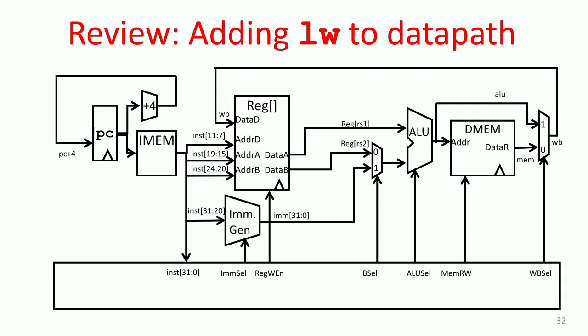The difference is now something's going to come from the register file and go into the data memory. So far we've only used the data memory for reading. So we're going to wire up to the right port of the data memory. And that's going to be RS2. We have to have a path from that to the data memory.